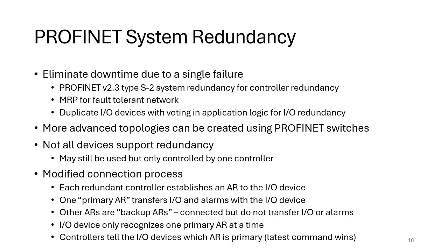As soon as we get to a second failure, what is the second failure? So for example, you might have two power supplies operating the system in redundant mode. If your first failure is the first power supply fails, you can survive that because you've got a second power supply. If your second failure is the second power supply goes down, then the whole system goes down. Same as if you lose two CPUs or you lose two duplicated I/O devices. So it's much harder to eliminate downtime due to dual failures than it is to a single failure, because you don't know what that second failure will be.